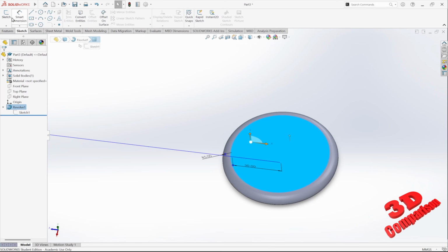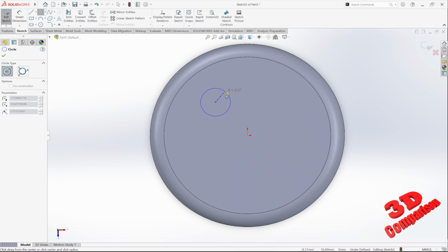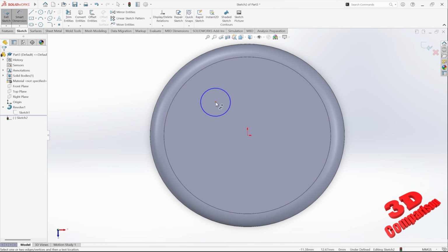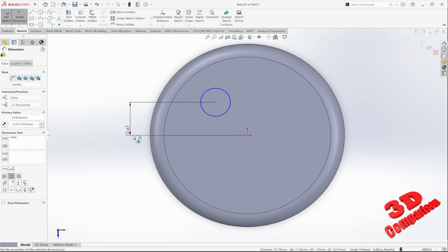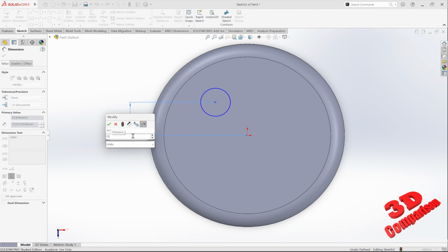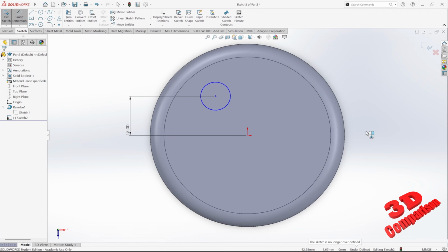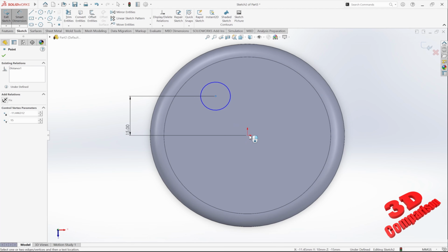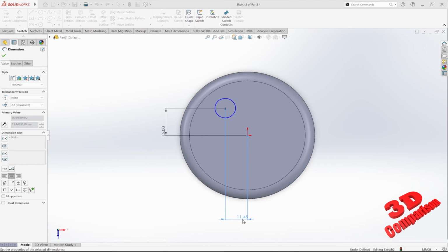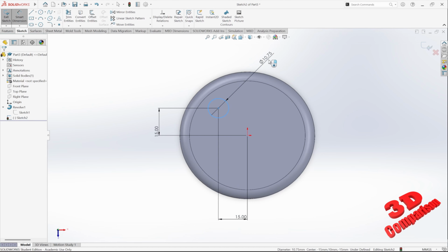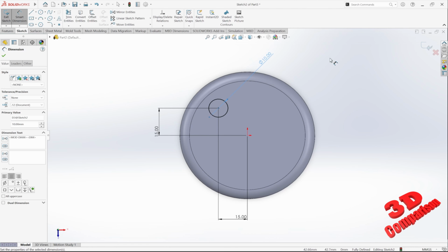Now, on the top section, I just want to create a simple circle because I want to see that drafting and how that angle will influence this. So I'm going to add the initial circle at 15 over here, also onto the other axis, so over here as well. I can add the dimensions, let's say 10 in this case.